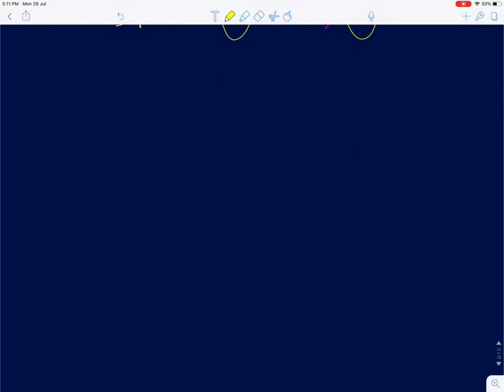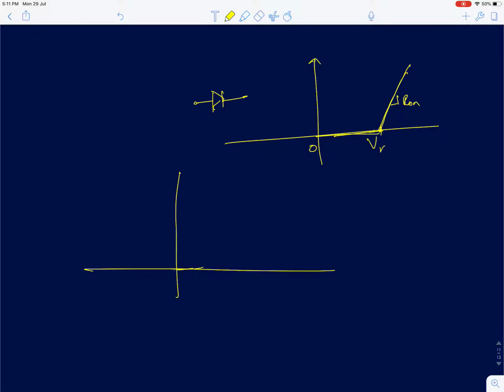I'll just cover one other thing which is done in slightly more advanced models for diodes. As I said, a diode can be modeled using a finite on resistance R on. Now when you need to model it more accurately, the diode characteristic, as I said, is an exponential characteristic, and the graph model we have used is going to be like this when there is a finite V gamma, and even if you assume a finite slope, it's going to be something like this.